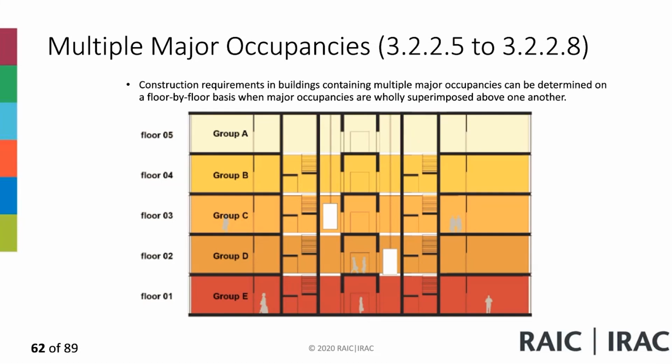Yeah, in table 311, we have major occupancy requirements. And then we have the classification of the building and the floor ratings. Again, if I want to base it on a group D building, I'll take the classification for group D building, and the rating of the floor here will be based on that classification. However, I have to make sure that I have the fire separation requirement between the major occupancies also. So you see, this is a complicated text, but let's do this.